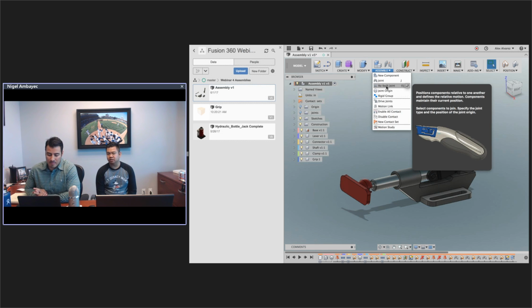Exactly. Yeah, so that's generally best practice. The same thing goes for Inventor when you're bringing in foreign CAD files. Same thing's going to happen. You're going to lose that design history, those joints and constraints. Go ahead and just build them as is, make them rigid, and you should be pretty good to go. And if you need to do motion, again, it's not too difficult to do that in Fusion or even Inventor or SolidWorks even. So not too bad at all.